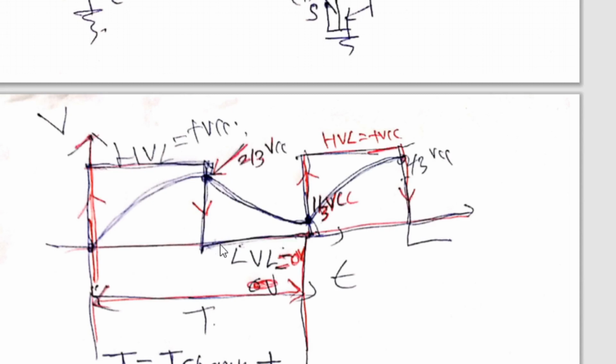Whenever the voltage changes from low to high, it is marked by the upgoing arrow. So this is called positive edge. And the total time T is the time between two adjacent positive edges or two adjacent negative edges. So like that here, this is the total time T.